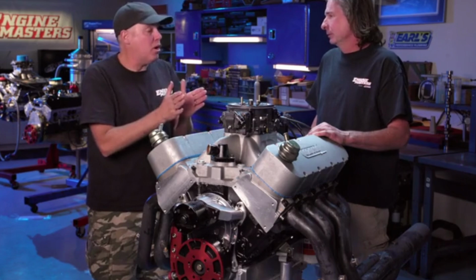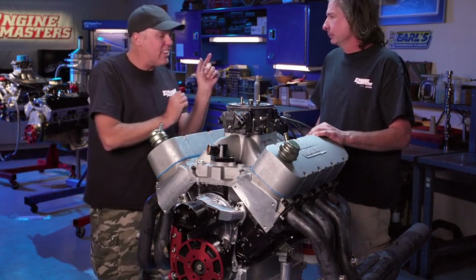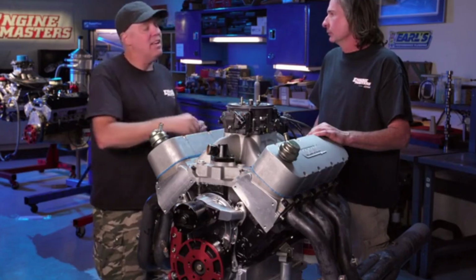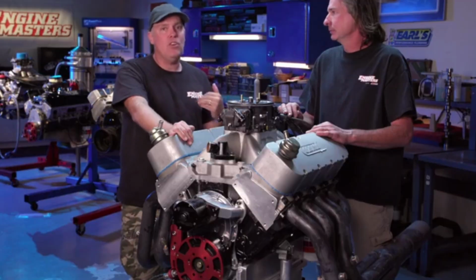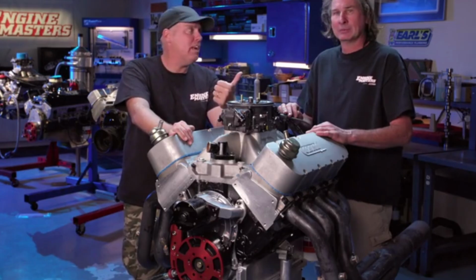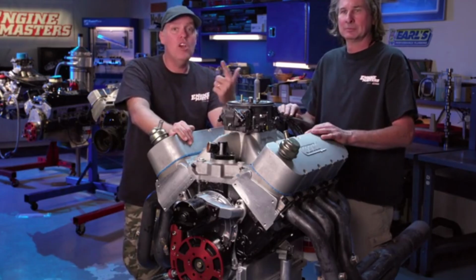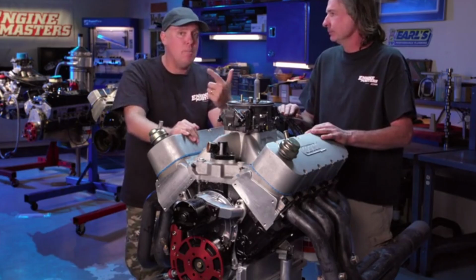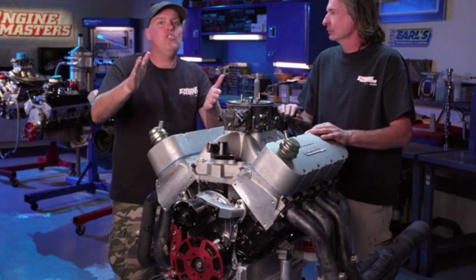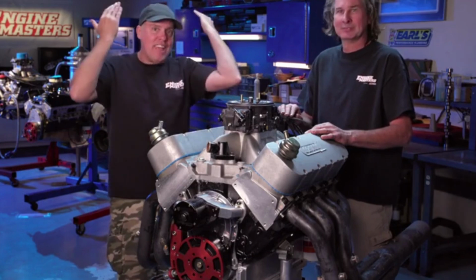And so the other part of my conclusion was that the slight differences that we saw at the bottom end and the really slight difference we saw at the very top end are attributable to other factors, like inertia at the bottom end and maybe some ring seating issues at the top end with the long rod. In my opinion, what you want to do is pick your stroke first, which is going to be based on displacement and piston speed and things like that. And the next thing you want to do is call like JE Pistons and design the best piston for your ring package. And once you've got that down, you connect the two with a connecting rod and you have a nice day and don't worry about it.